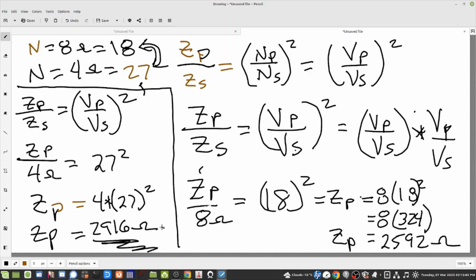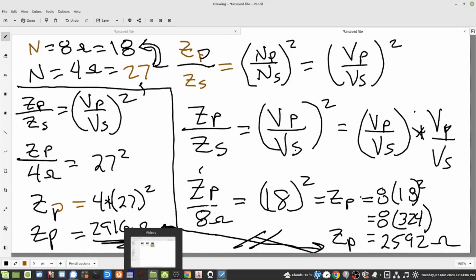All right, you can see the problem. These should be the same reflected primary impedances. They are not. So we're 400 ohms off. Now the question is, is it me? Or is it this transformer? Now I suppose it's possible. There's a real cluster in there. I suppose it's possible that I did not clean up all the circuitry, but I think I did, so I don't know. This could be just a bad transformer.